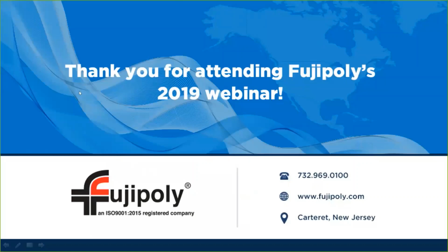Okay, all right, another question on the UL flammability ratings of putty materials. They're all rated V0 for flammability, and we have our UL yellow cards available on the database for these materials. Another question is, what is the operating temperature range? Recommended is negative 40 C to 150 C, and higher temperatures are okay for short durations. Another question is, what are the thermal conductivity values of the putties? The range would be from 2.8 watts per meter Kelvin up to 13 watts per meter Kelvin.